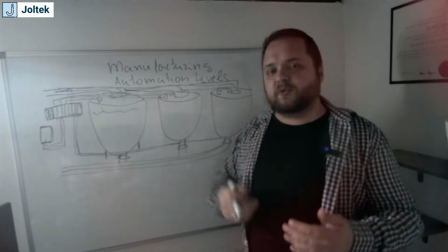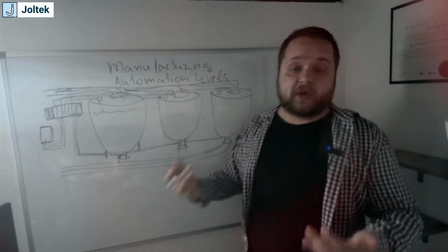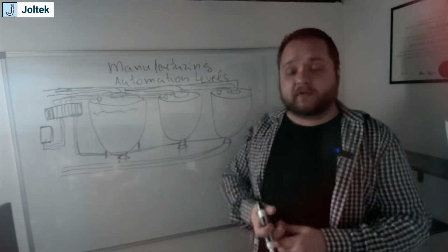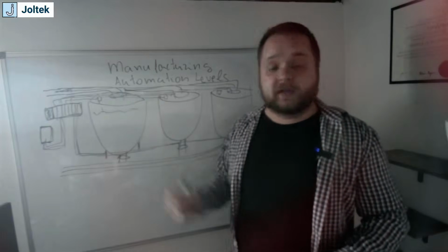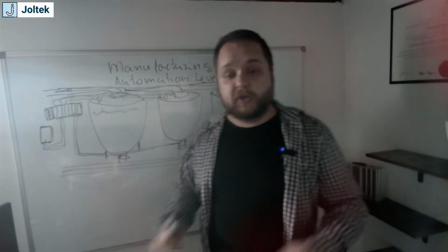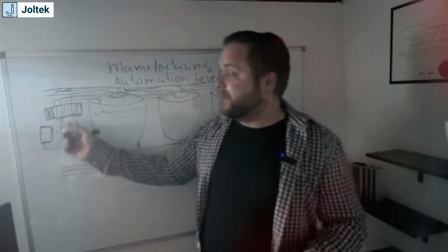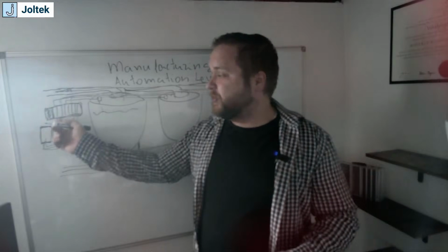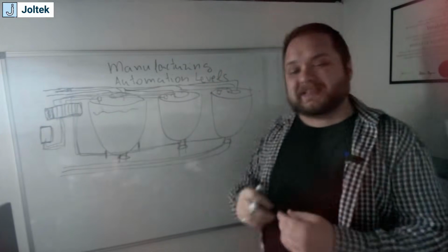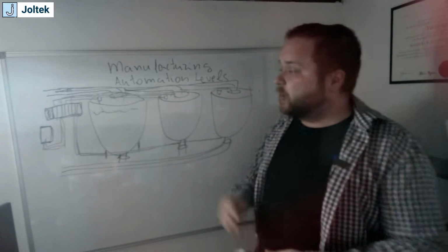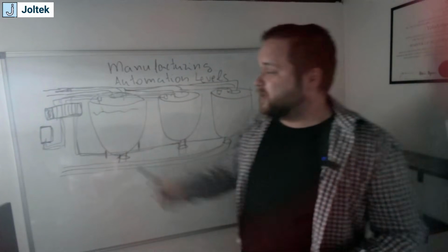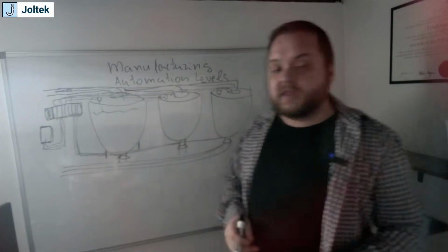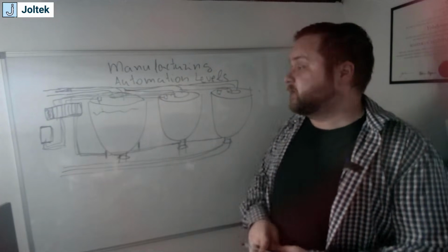So ultimately you don't need to readjust the speed every single time. All you're doing is you have 3 set points, and based on the fill level of the tank or maybe the discharge that's going into a different system, you're going to be controlling that VFD again via digital outputs. And so this is the second layer of automation where you basically just have a PLC and a couple of IO points and a couple of peripherals that will be utilized in the system.